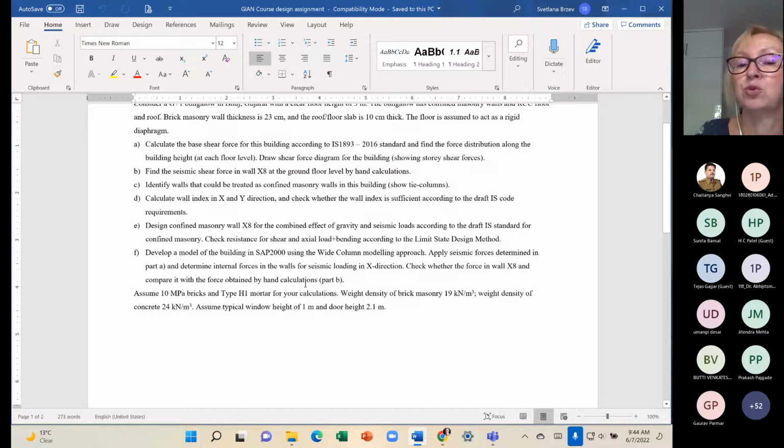So that is going to give you a sense of what you need in terms of masonry properties if you want to make this work. Frankly speaking, and I believe you agree with me, for a G+1 building, 23 centimeter thick walls should be okay. Why would you choose thicker than that?